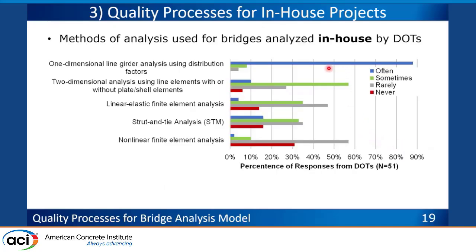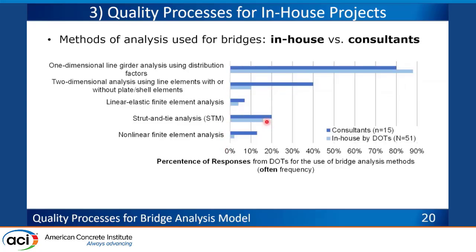You can see the analysis methods in-house. Definitely line girder analysis is represented as the most used. The least used is nonlinear finite element. Linear elastic finite element is also used very rarely. So we can see line girder as well as strut and tie used in-house by DOTs.